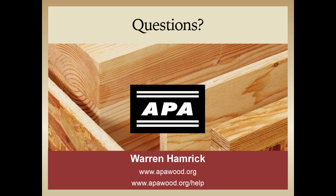You know, a lot of these details are right in the residential codes, and there's an item with the single top plate that I've run into some confusion in the field, and we'll get into single top plate details in a lot more detail later in this presentation. That's the only area of concern that I've gotten. For the most part, just to directly answer your question, no. I've had very little to no issue with building officials having an issue with advanced framing. Wonderful. So I heard you say a lot of the details are code prescribed, and that's in the IRC legacy codes?